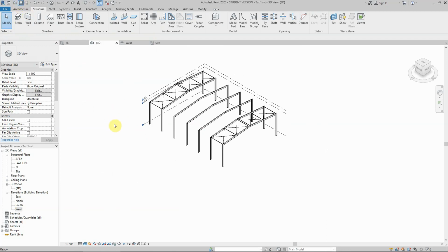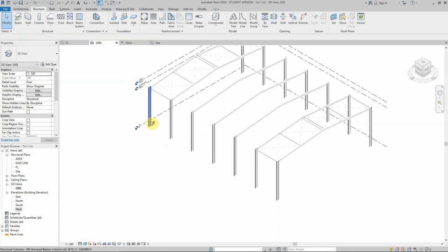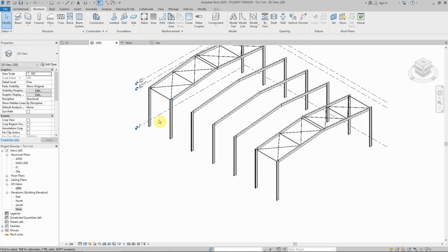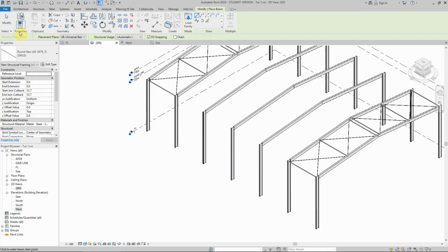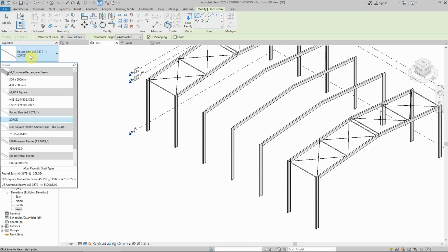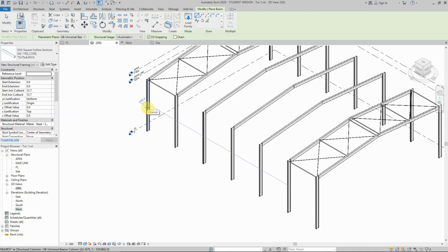Save, and that would be our pricing already done for the roof. We'll create similar pricing now for the walls. The same approach, I'll just draw the struts between them in a form of a beam. The strut is made of the same size, I'm assuming 75 by 75, so I'll just use that, and snap to middle SM from here to there.